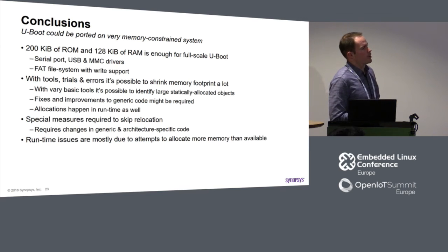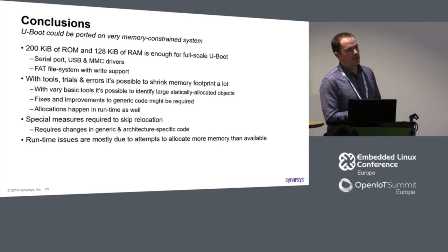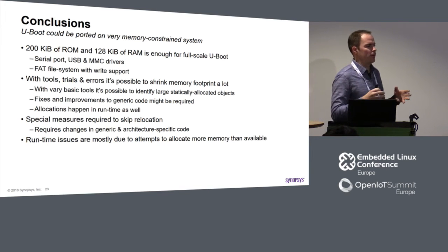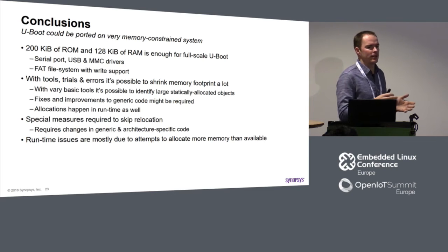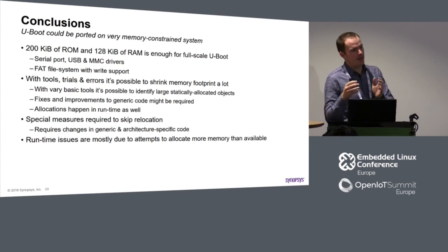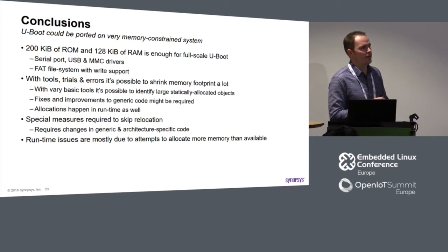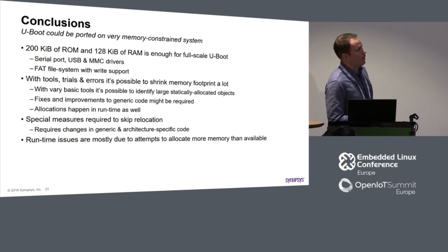What is also good to remember when you are fighting with a limited memory situation is that allocation happens not only statically during compilation, but at runtime as well. And it happens not only in the heap, but in the stack as well. And it is always a very complicated problem when you have a stack overflow.